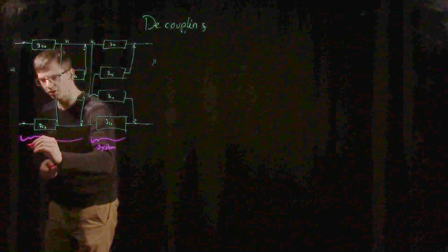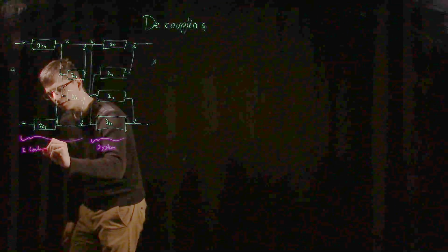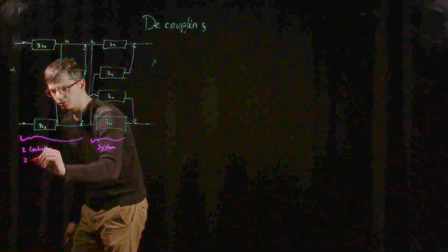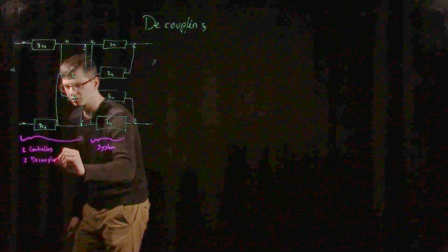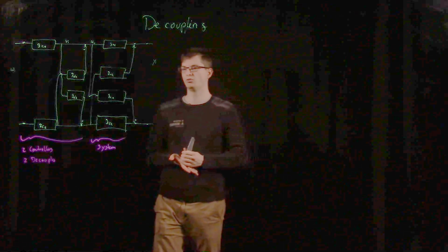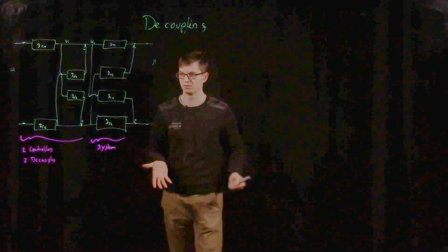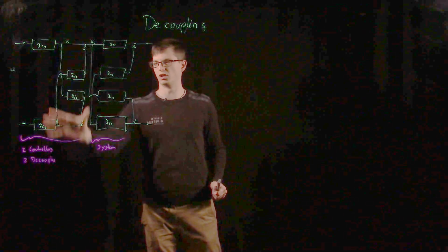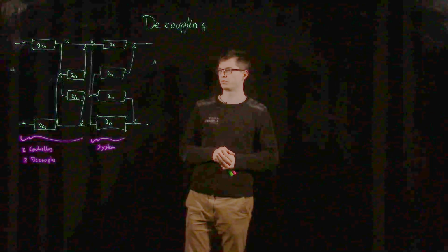On one side, those are two controllers and two decouplers. What you would implement in the real world is one plant side, one system behavior, and on the other side, one big controller. And this controller has those four parts.